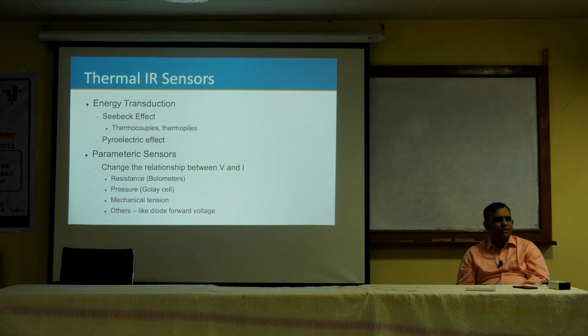Remember, you have done quite a lot of diode equations and transistor equations. Temperature always appears one way or other. If nothing else, kT, where k is the Boltzmann constant and T is the temperature, appears at many locations. So wherever it appears, whatever my output of the semiconductor material is going to be, it's going to be temperature dependent. So I can use that as a temperature sensor. If nothing else, you take a diode, just design a simple diode, measure its current, that is a temperature sensor, if you can scale it down into very small amounts.